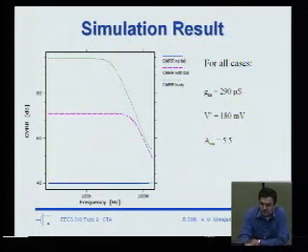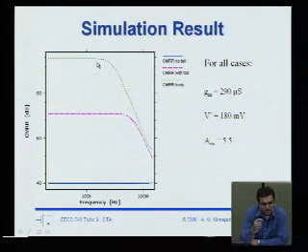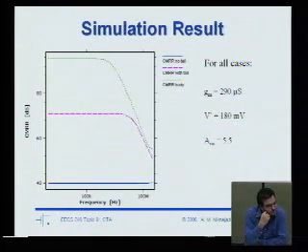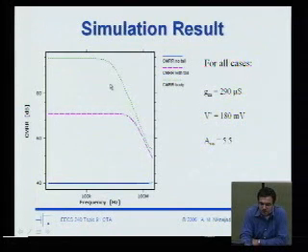Really, really nice. Why is it that the frequency starts dropping faster for the PMOS devices? I used to thinking that you kind of keep the GM the same, so the PMOS should be large, so the capacitance. But that's only twice. I don't know why it's kind of like more than twice. Yeah, that's a small factor, and here it's actually a huge factor, right?